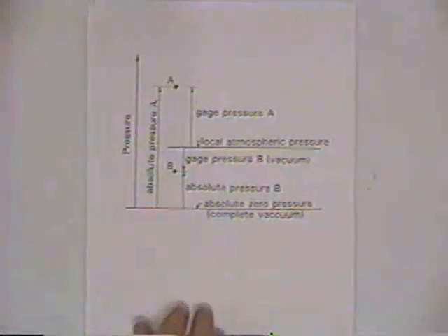Moving into pressure, as we introduce the different properties and terms we'll be working with this evening, we can measure pressure from whatever reference we'd like, and the two typical reference datums are either absolute pressure, using absolute zero as the datum, or in many engineering applications, a majority in fact, we use atmospheric pressure as our reference datum, and we call that gauge pressure. Now, the absolute pressure is the gauge pressure plus atmospheric pressure, and we can use this diagram to visualize that.